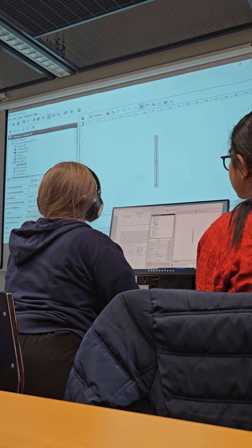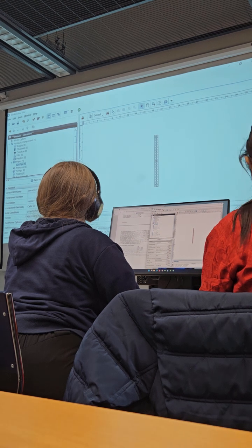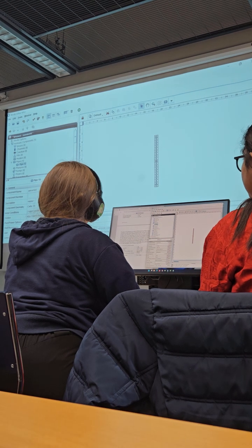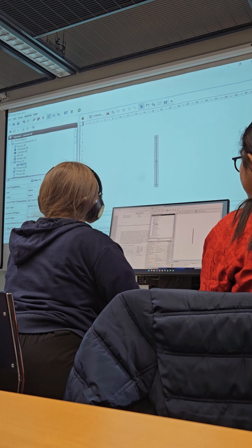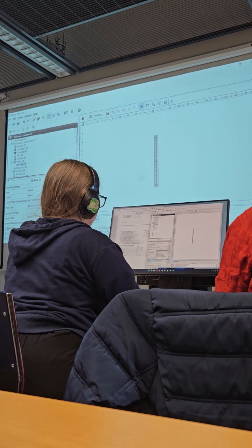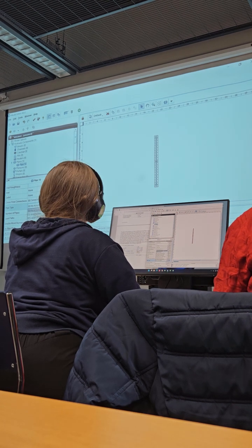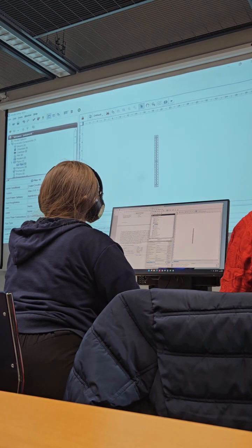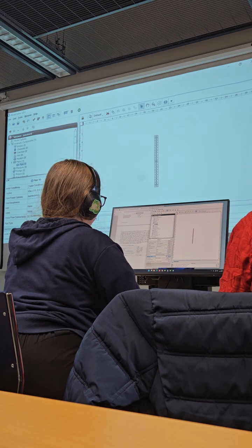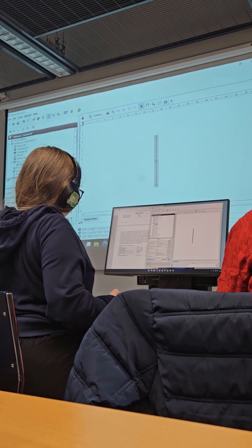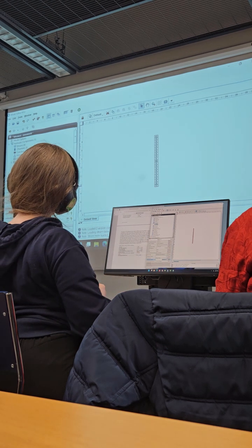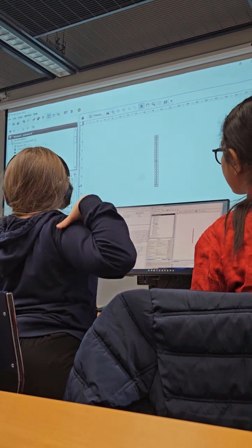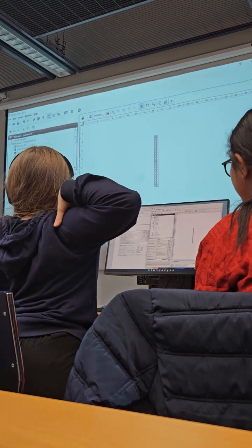So we can go, we need to set the pipe type here. It is a default one, no accumulator. We just need to change it to model 7, pre-flood heat structure. And here is the one unknown variable for the pipe. We need to define its unheated fraction.